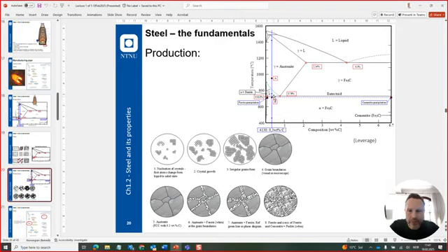Going down below the eutectoid line, you have the state 8 here, and you will have a combination of ferrite and also cementite, or what is called pearlite. Now these are exaggerated for you guys, so that you understand that even a solid piece of steel actually changes nature.